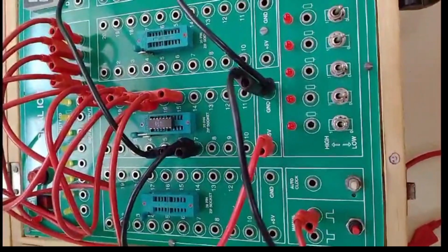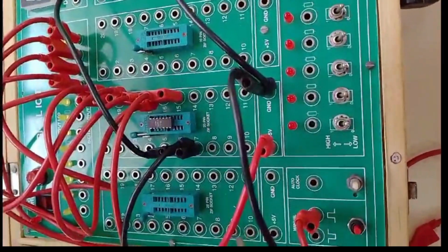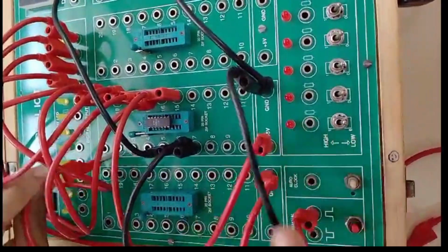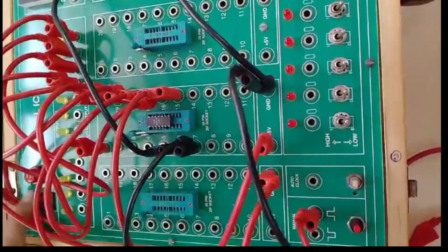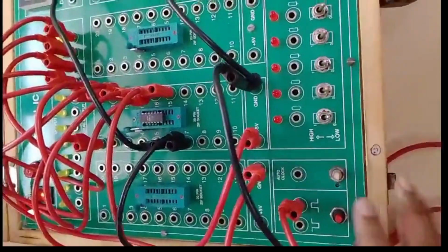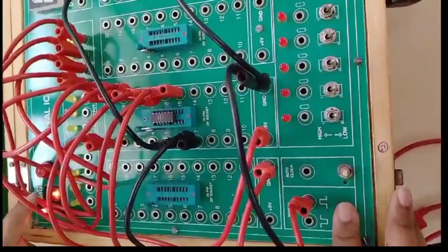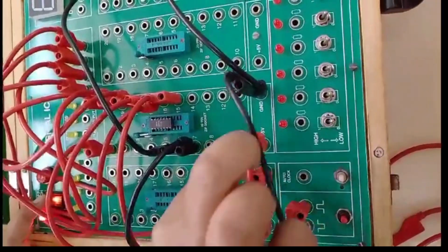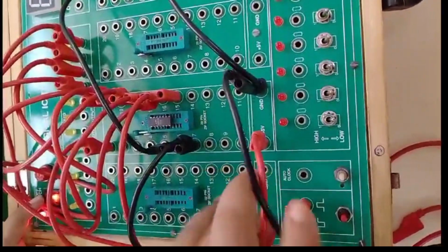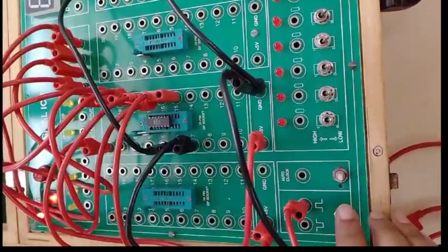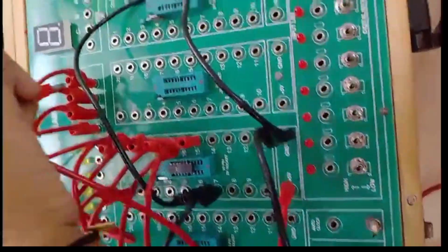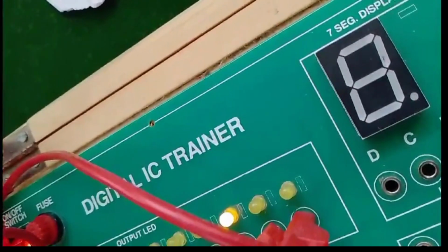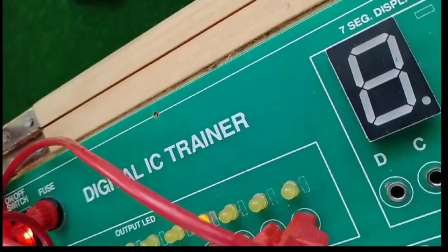Now connect one wire in pin number 1, and initially that wire is connected to ground. Now just apply a few clocks and clear all flip-flops. Now remove the ground and connect that wire to VCC. Just apply a single pulse, due to which QA becomes 1. Now just observe the operation of QA, QB, QC, QD in the ring counter.